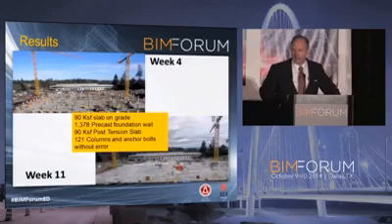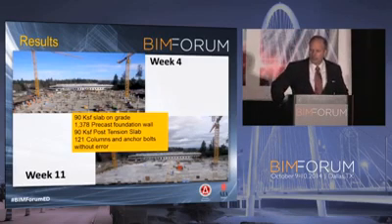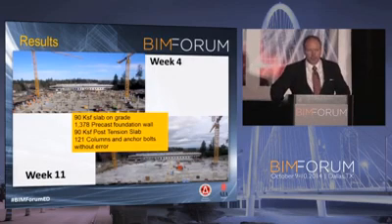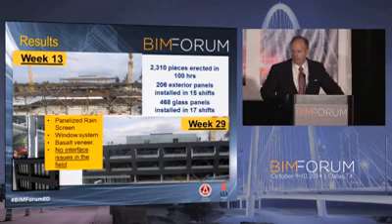What are the results? On that job that we had to take 169 days out of the schedule, you can see up in the upper right-hand corner, week 4, week 11, 90,000 square feet of slab on grade installed, 1,378 precast foundation panels put in 2.5 days. Again, your external setup. 90,000 square feet of post-tension slab done. No blockouts in the wrong spot, and 121 column anchor bolts installed, all perfect. Week 13, 2,310 pieces of steel installed in 100 hours.